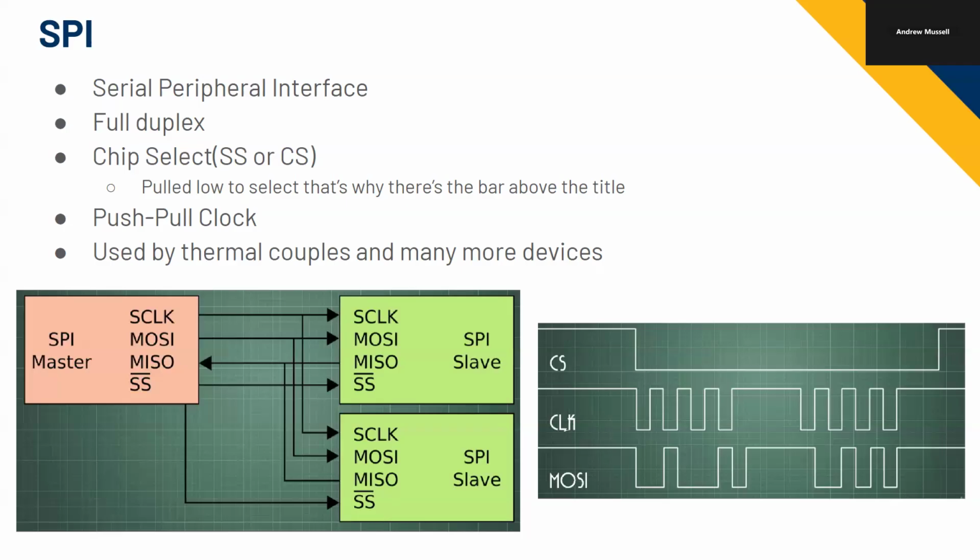I'm so confused on how it works. It's all good. It looks like the clock is not in sync with the MOSI, and it was like that for I2C too. It's in sync with the edges, not with the high and the low. The edges of the clock, I mean these vertical lines. So we only clock data on the rising edges.